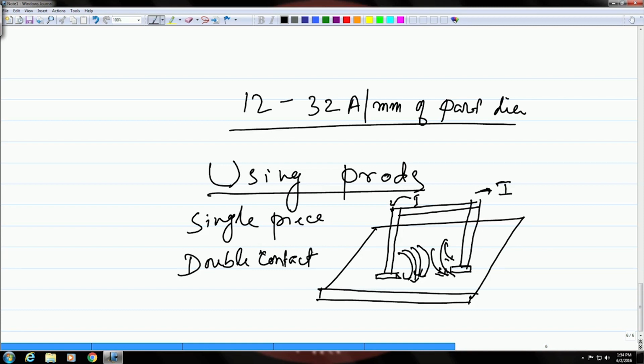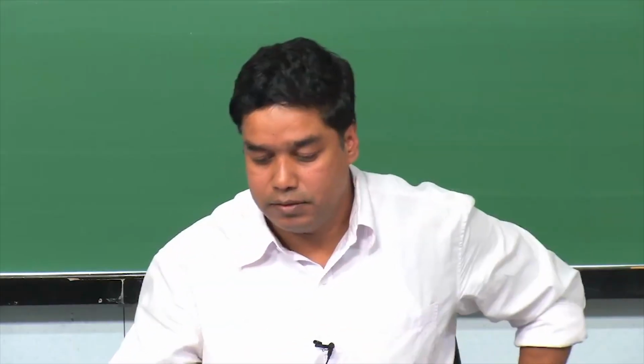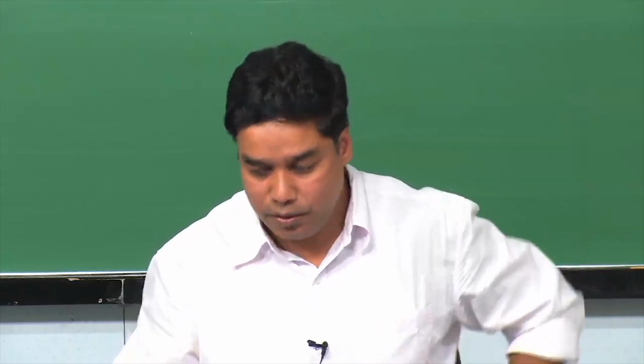Okay. So, it is carrying the current and it is in contact with the part directly. So, you need to make sure that there is no loose contact. So, it should be pressurized against the part. Therefore, sometimes pressure pads are also provided to make intimate contact, so that there is no loose electrical contact and there is no electrical arcing due to loose contact.